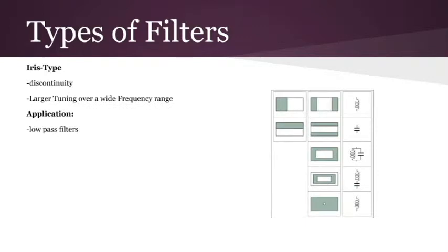An iris is a thin metal plate across the waveguide, with one or more holes in it. It is found that abrupt changes in a waveguide will give rise to a discontinuity that will create standing waves. However, gradual changes in impedance do not cause this. Irises create a discontinuity by exciting modes that are soon to be gone.